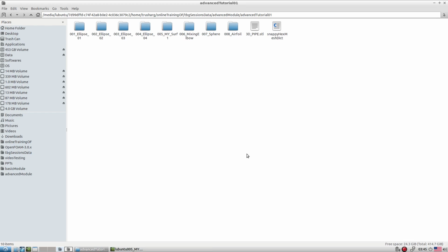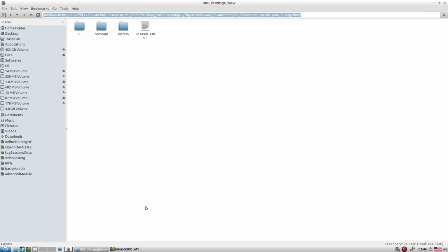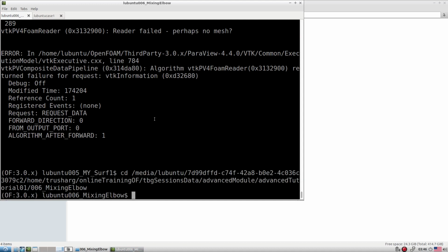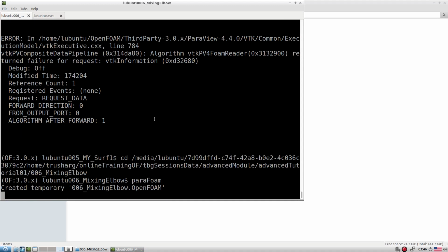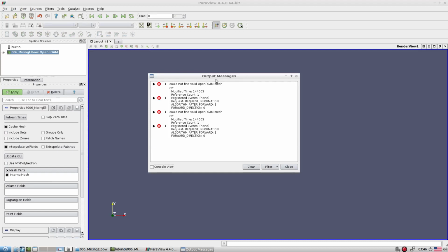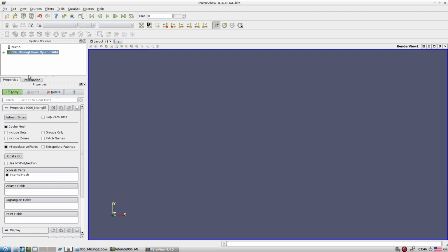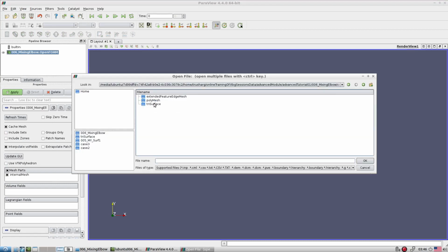So let's quickly go towards internal flow type of calculations, where we try to do the meshing for something like a mixing elbow class of three-dimensional domain. Okay, so let's first go to the area and explore how the STL file looks. Until you have some mesh, it always gives you an error, so don't worry about that part, but go straight to the tri surface and look at the STL file.